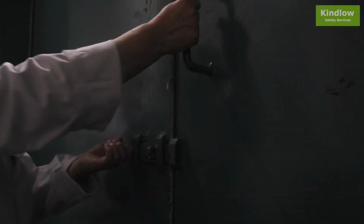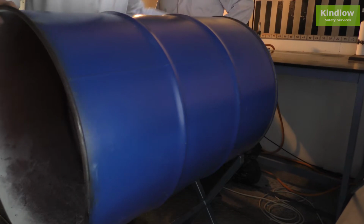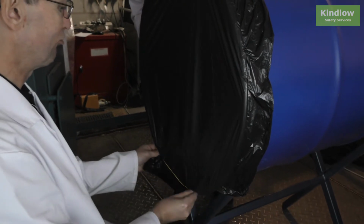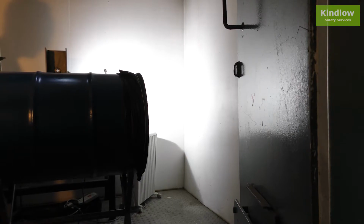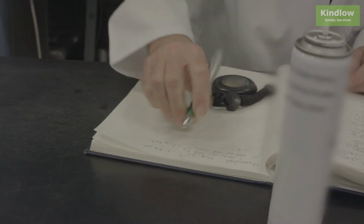The purpose of the enclosed space ignition test is to measure the likelihood of a spray used in an enclosed space to ignite. In the enclosed space ignition test, the aerosol is sprayed into a drum of known volume, which contains a candle and a deflector. The open end is covered with a plastic film. The aerosol is sprayed into the drum until ignition occurs. From the elapsed time and weight of product, the time equivalent and deflagration density can be calculated.